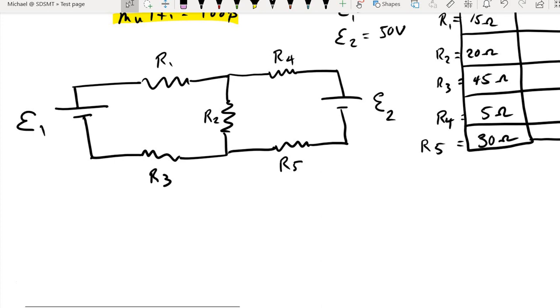And if we look at what's happening, I'll switch over to red here. So far, we know how to combine resistors in series, and we know how to combine them in parallel. So do we have anything in this picture that matches one of those definitions? You might think, well, maybe R1, R2, and R3 are in series. They are connected one after another, but we also have other stuff connected in between, and so the definition of series does not hold up.